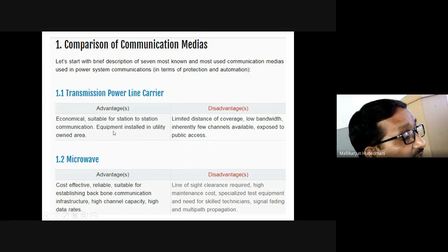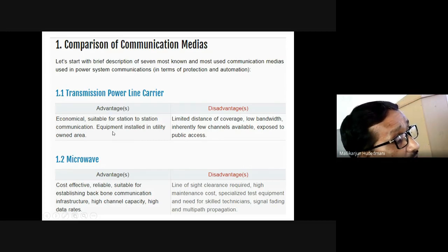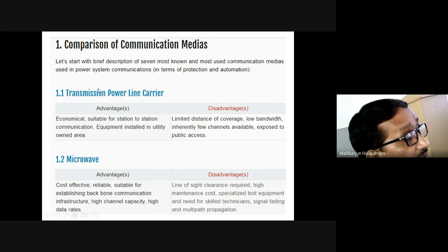At the end of the transmission line and the beginning of the transmission line, if I install this LC circuit and tune it, voice can be mixed over the transmission line, and on the other side you can listen to it after demodulation. This is how power line carrier communication makes use of the existing transmission grid infrastructure, mixing the particular carrier frequency signals on it and extracting them on the other side.